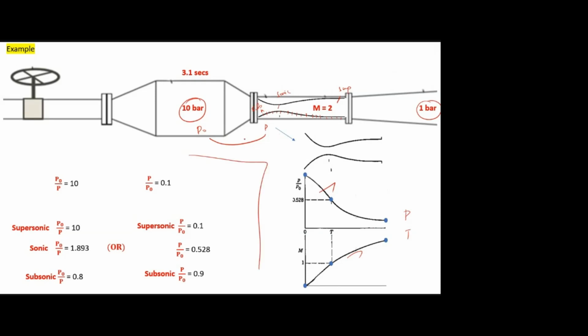So now for that experiment, actually we have taken the reading after 3.1 seconds. In the normal subsonic internal flow procedure, if you remember, you first switch on the wind tunnel, then wait for 2 to 3 minutes to get the flow stabilized, then take the reading. We wait 2 to 3 minutes to get the fully developed flow.